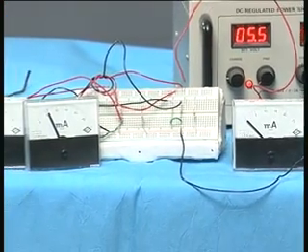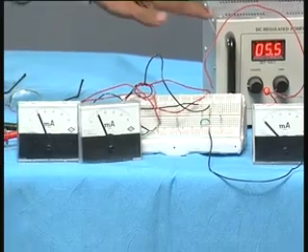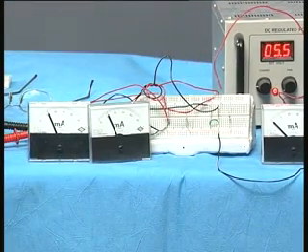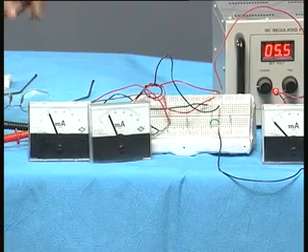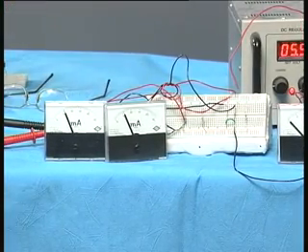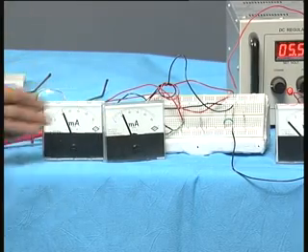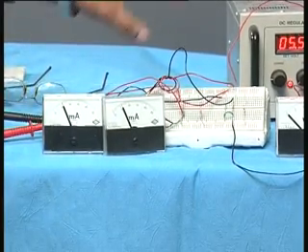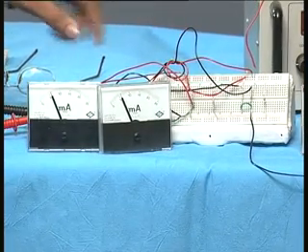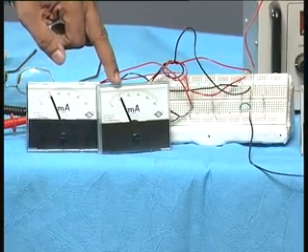So, you can see, because I have 6 volts appearing across both the 1000 ohm resistors, both the resistors will generate 6 milliamperes independently, and the total current will be the sum of the two currents. Therefore, a parallel combination divides current, and they have the same voltage, 6 volts across them. 6 volts divided by 1000 is 6 milliamperes, here also it is 6 milliamperes.